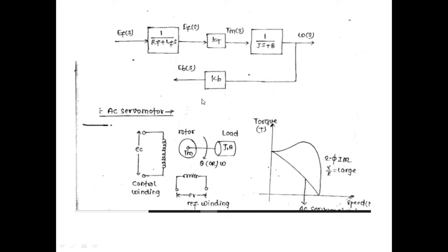As I have discussed, in a closed loop control system, error is responsible for minimizing error. That means the error produces the actuating quantity which controls the error, which compensates the error. So obviously, this winding should be fed from a differential amplifier or something which is doing the task of differential. How can I explain it? Let us say I am going to implement a position control.